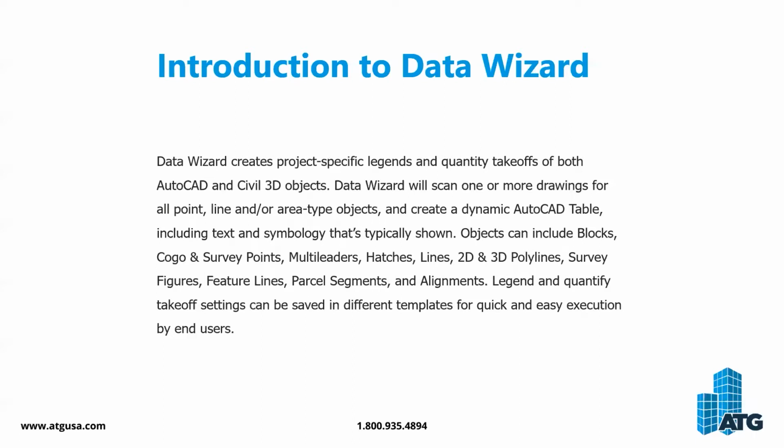The Data Wizard will scan one or more drawings for all point, line, and/or area type objects and create a dynamic AutoCAD table, which will include text and symbology that's typically shown. Objects can include your blocks, COGO and survey points, multi-leaders, hatches, lines, 2D and 3D polylines, survey figures, feature lines, partial segments, and alignments. Legend and quantity takeoff settings can be saved in different templates for quick and easy execution by end users.